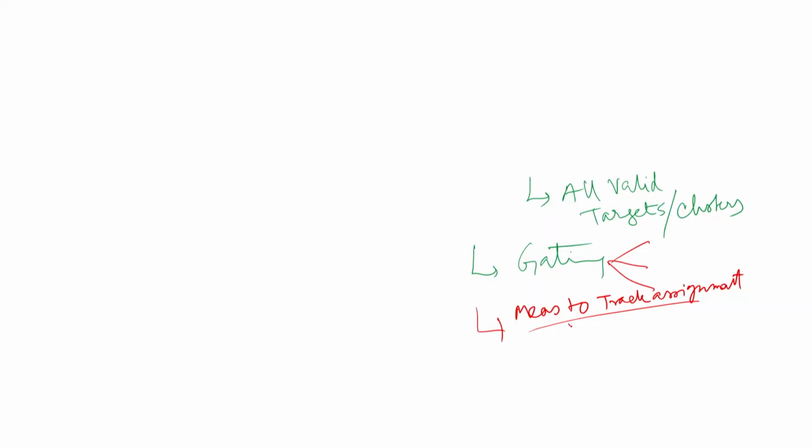Here there are 3 methods: nearest neighbor methods, the probabilistic data association method, which is a different kind of filtering, Kalman filter only an extended version, and another one, multi-hypothesis tracking. This is done. Once I get this step, then I will do filtering.